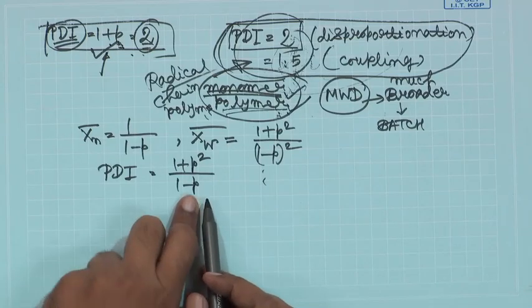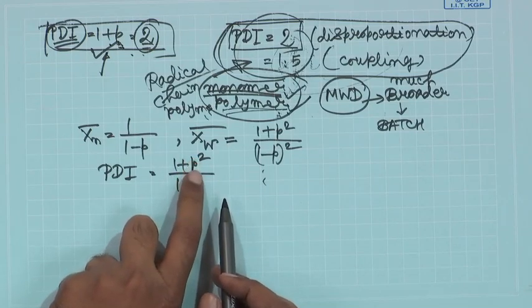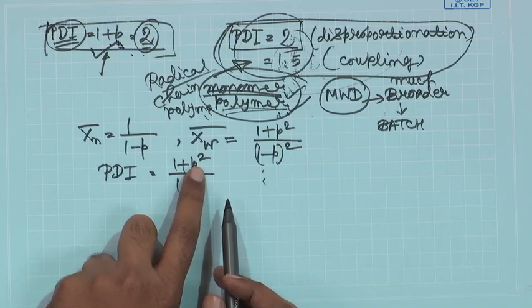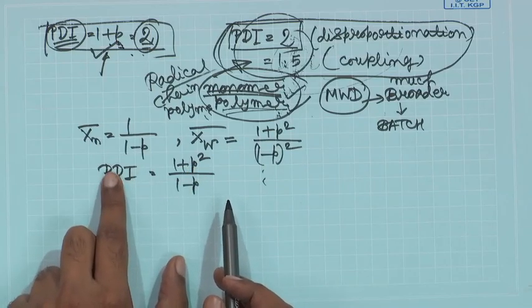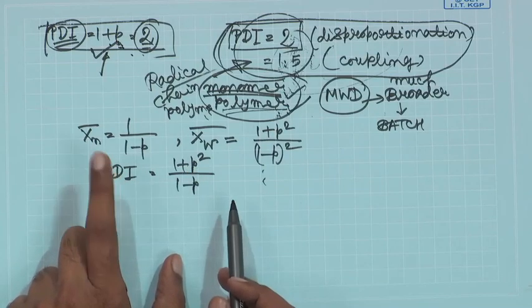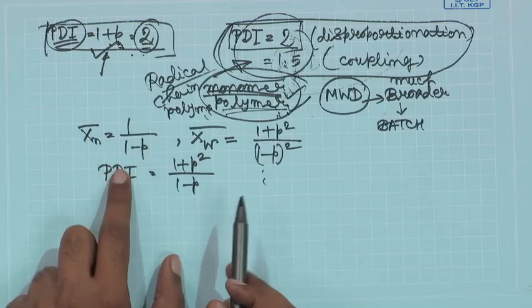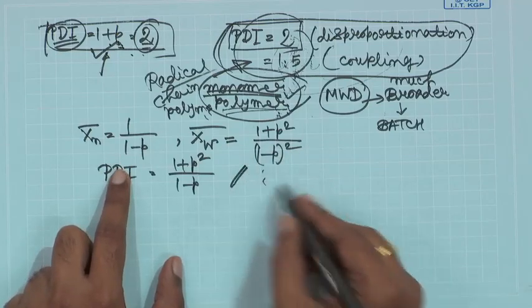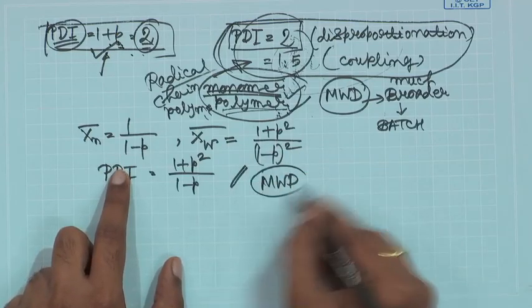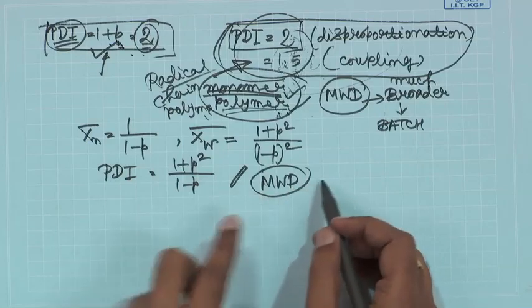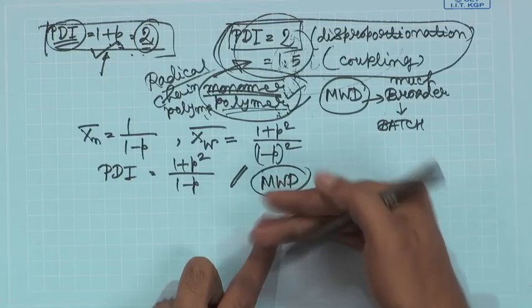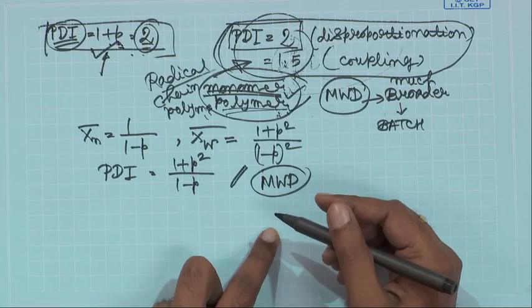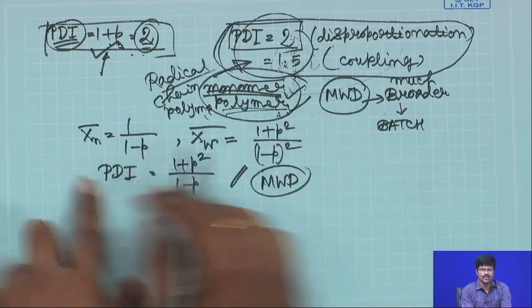So, in a CSTR, if you are looking for very high conversion, what is happening? If you go to higher and higher conversion, your PDI goes up towards a very high value. So, in a CSTR your molecular weight distribution will be much wider, if you are targeting very high conversion, as compared to a batch reactor for a step polymerization.